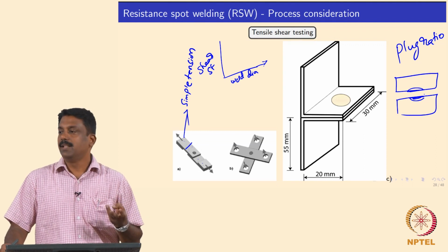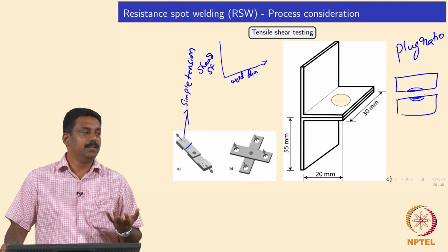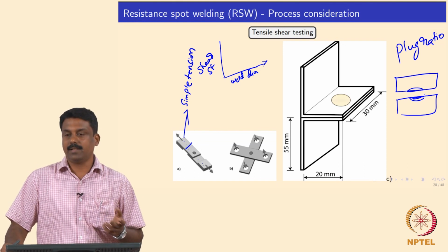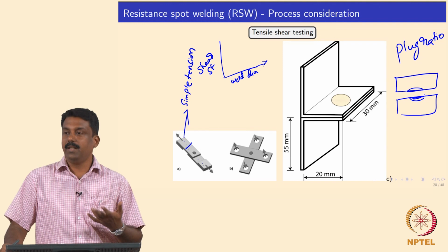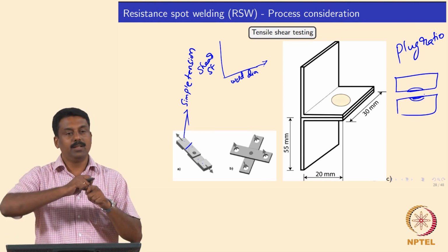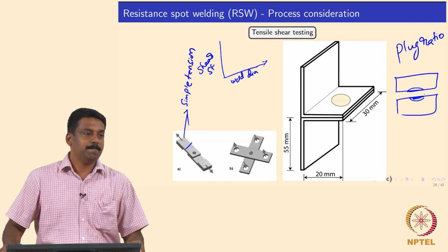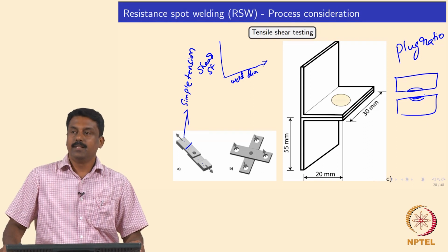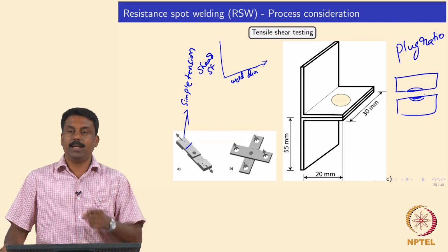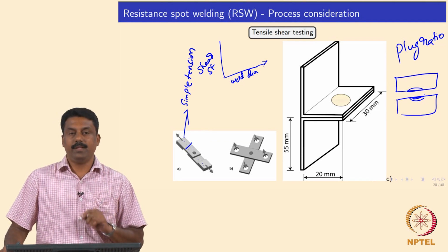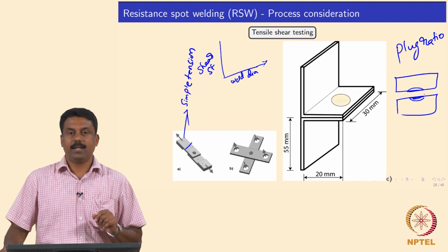That means that the weld is not that brittle, the interface is not really segregated, it does not have a brittleness at the weld center line. So, if the weld center line is completely embrittled, what happens when you are applying load? It will open, isn't it? Complete interface failure will happen, right? It's clear. So, we will have to identify the strength plus the failure mechanism in order to quantify the weld metal properties of the resistance spot weld, right.